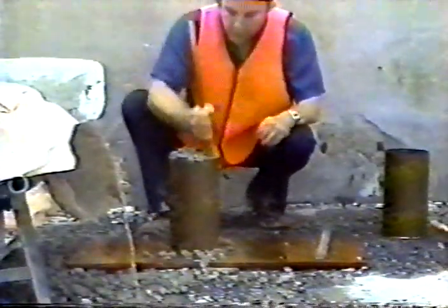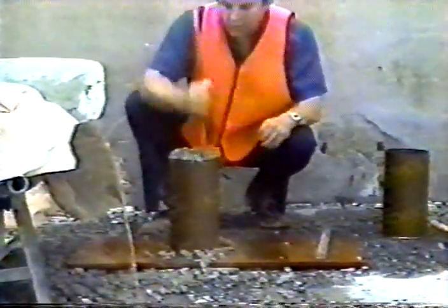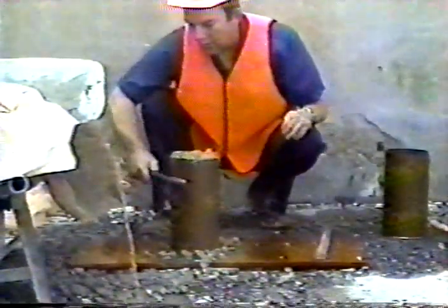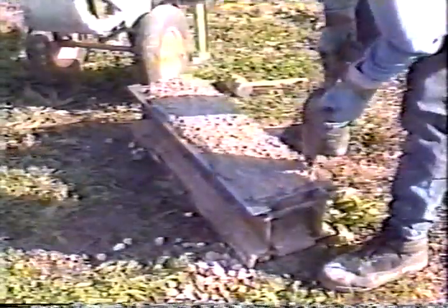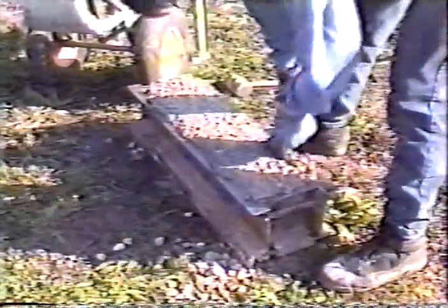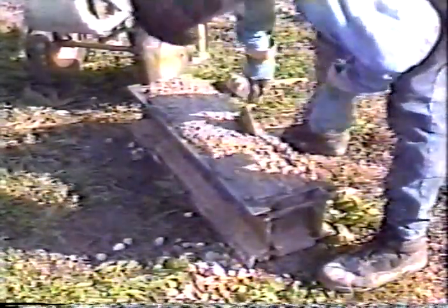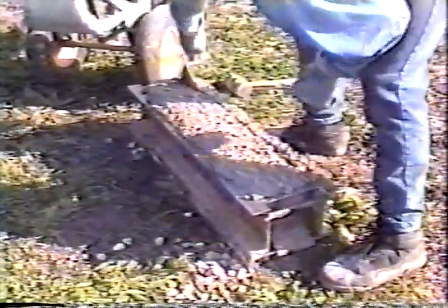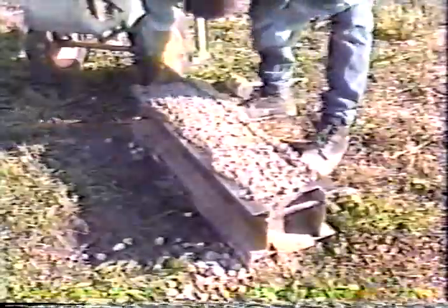After each layer is consolidated, the outsides of the mold are tapped lightly 10 to 15 times to close any holes left by the rod or vibrator. When beams are made, the tapping of the mold should be followed by spading the concrete along the sides and ends with a trowel or other suitable tool. To finish the cylinders or beams, a small excess of concrete is added to the surface, but not more than 1/4 inch. Then the surface is struck off.